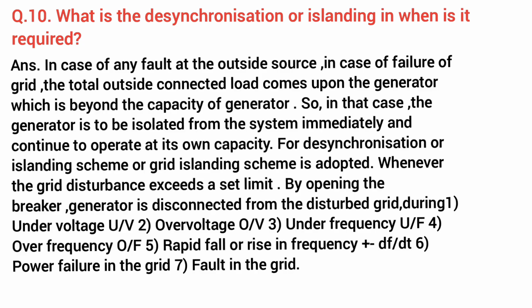1. Under voltage, U divided by V. 2. Over voltage, O divided by V. 3. Under frequency, U divided by F. 4. Over frequency, O divided by F. 5. Rapid fall or rise in frequency, plus minus dF divided by dt. 6. Power failure in the grid. 7. Fault in the grid.